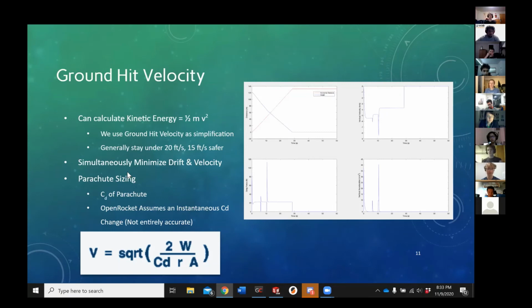So take accelerations from OpenRocket with a grain of salt. Another thing to consider is that there may be some damping in the shock cord itself. The shock cord can help with minimizing shock load. So what OpenRocket gives you may not be accurate.